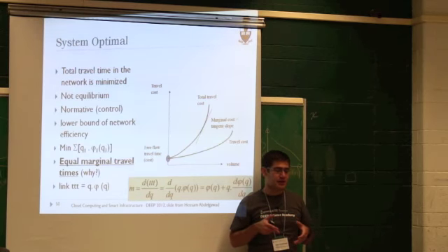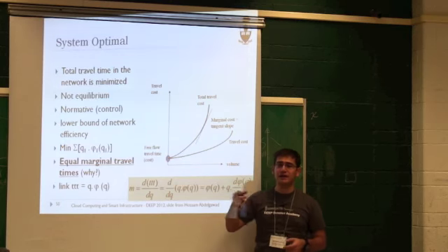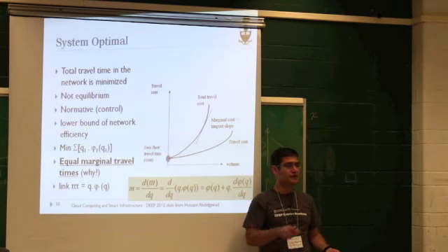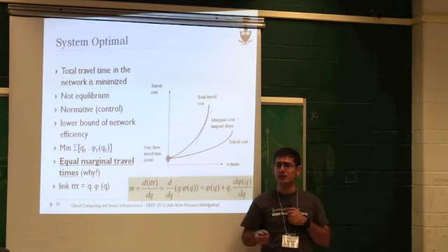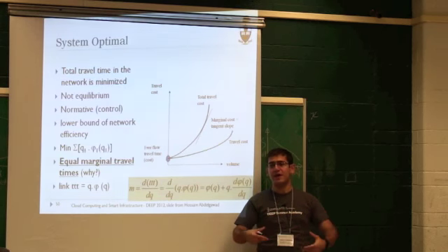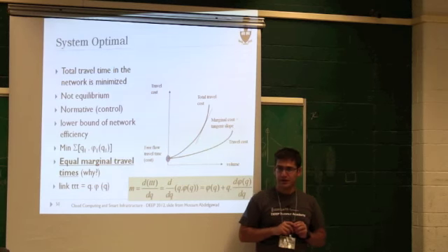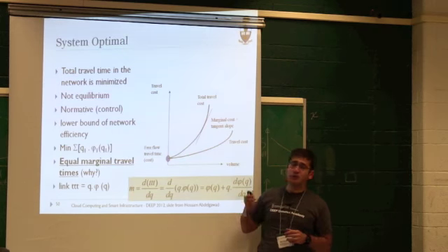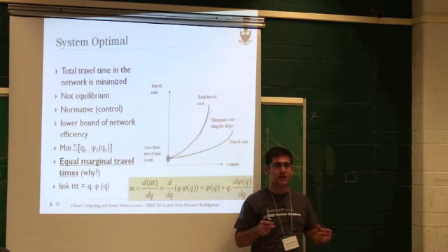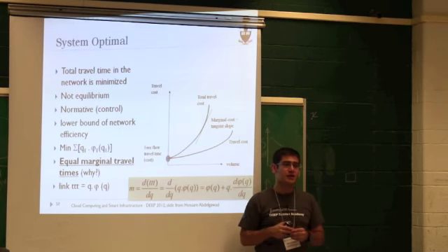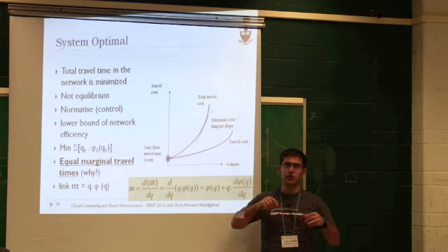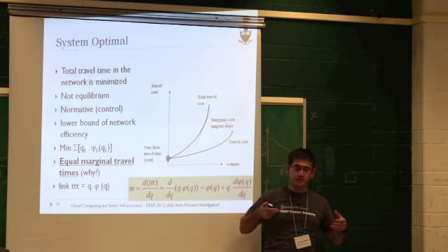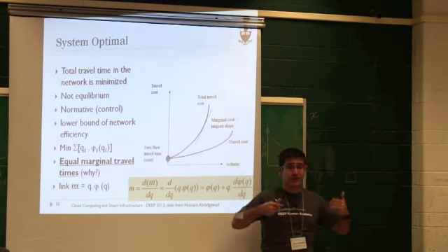What would happen if people start acting selfishly is I end up getting user equilibrium again. If people say, okay, I don't want to arrive 5 minutes late, I want to go to the other route, you get to user equilibrium. What ends up happening is everyone suffers together. So it's like game theory. Yes, so user equilibrium assumes rational behavior, where you have basically selfish behavior, and you don't care what someone else does. But with system optimal, this is what is actually the best.